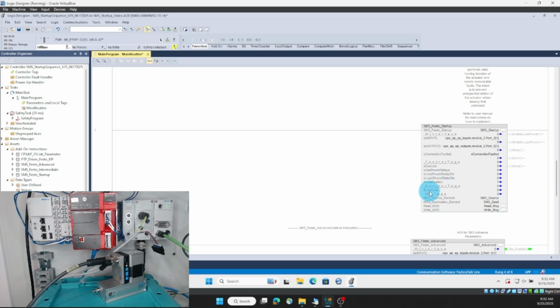Now this I error code shows the errors that occur during the steps of the AOI. Although if you get an error in the message instruction, you'll need to look at the diagnostics in the message instruction itself, or if there's an IO link related error, you can observe that in one of the original AOIs. So this error code is strictly for the steps that occur in the AOI. So for this I home position, I'm going to leave this as 1, so I want to end it in the in position, like what's currently shown in the hardware.